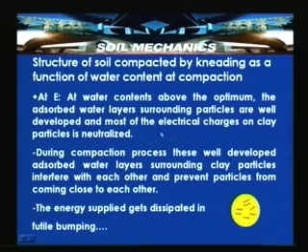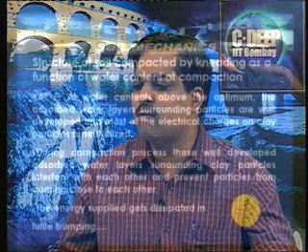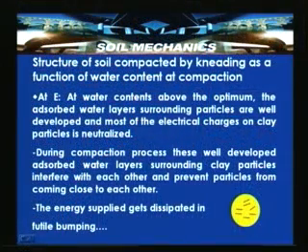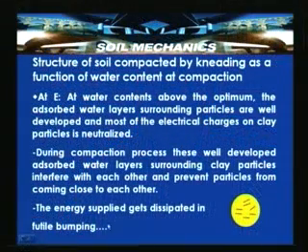Now the neutralization of the clay particles has occurred, and during the compaction process, these well developed adsorbed water layers surrounding the clay particles interfere with each other and prevent particles from coming close to each other, because the adsorbed water layers are now completely developed.